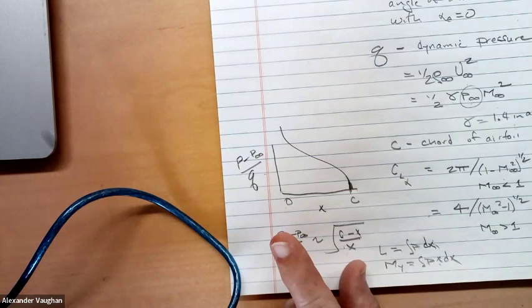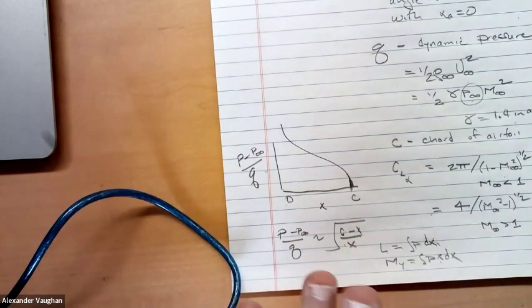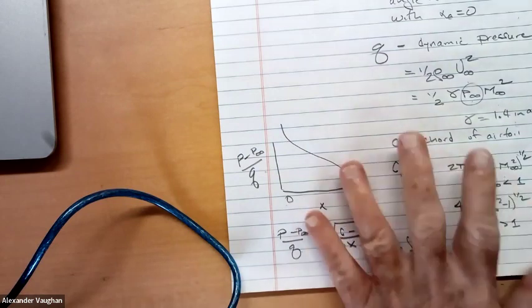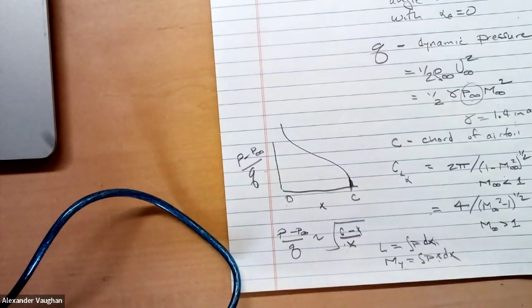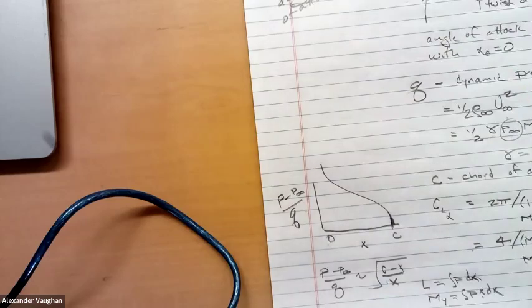It doesn't really go to infinity at the leading edge. It turns out if you add viscosity to the aerodynamic model, it's finite. If I run a computational fluid dynamics code, I get a finite answer. But anyway, that gives you a little background, probably tells you more than you really need to know to discuss divergence. But my point is that these numbers didn't just pop out of the hat. They actually come from a classical aerodynamic theory, which we're going to discuss later on.